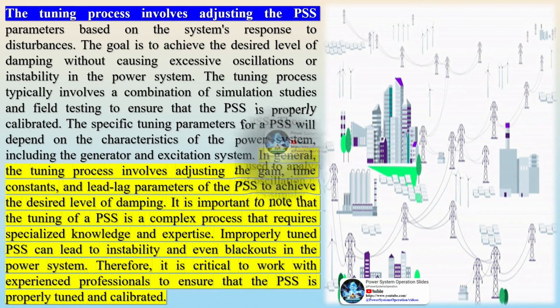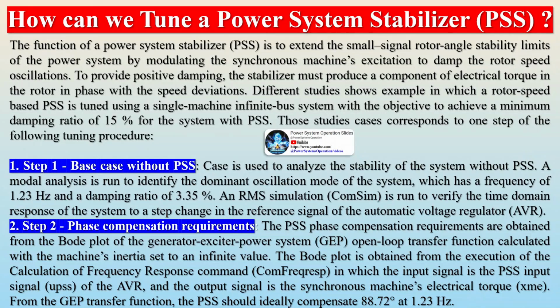The following scripts provided in the scripts folder of the project library can be used to aid in the tuning process. DPL command lead_lag_time_constants calculates the time constants of two first-order lead lag blocks for given center frequencies and maximum angles. Python command wrap_to_180 wraps the results of the phase Bode plot to plus or minus 180 degrees. It must be executed while the plot page with the Bode plot results is being displayed.